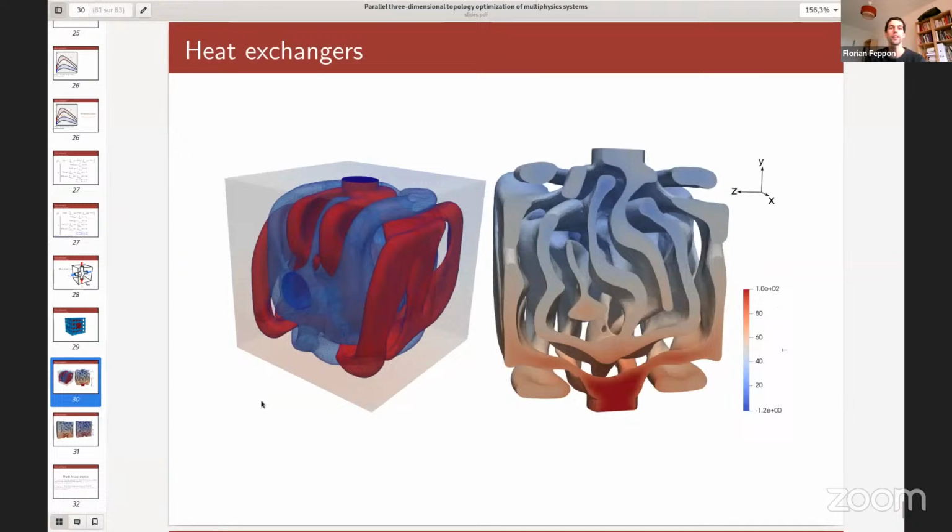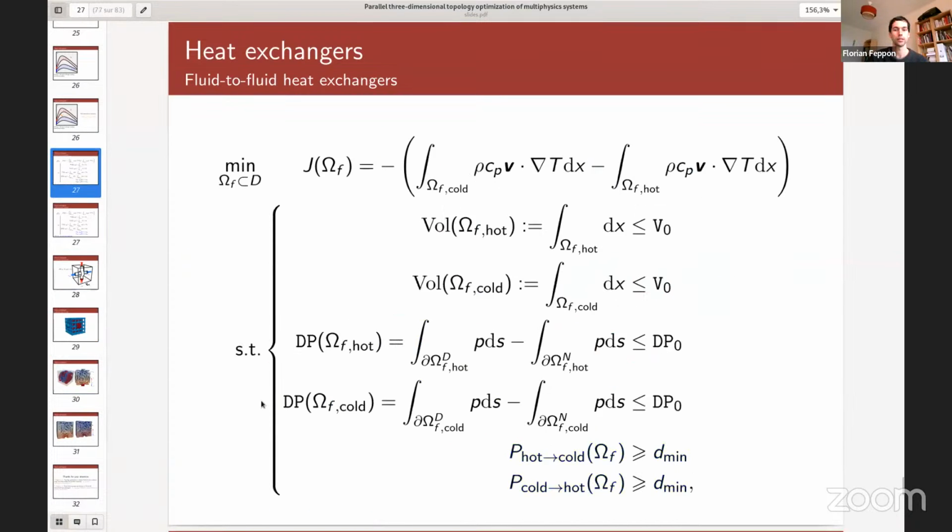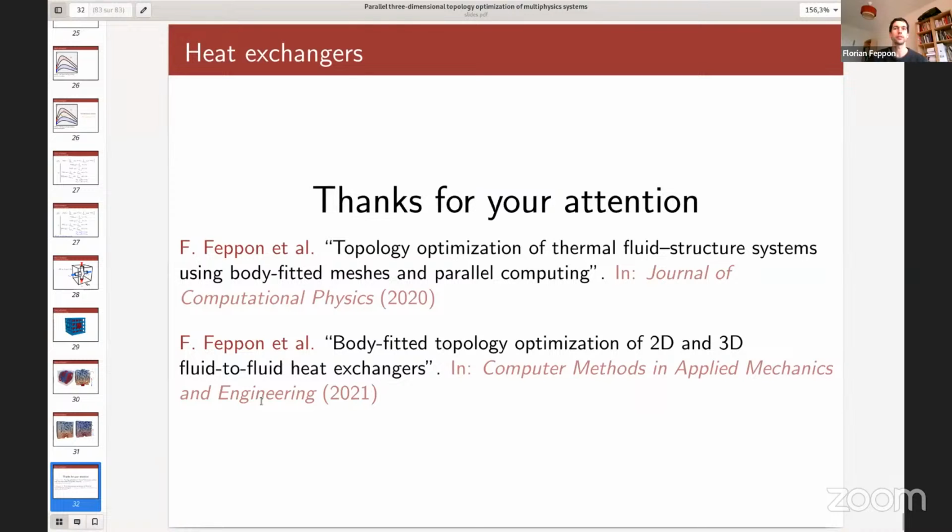Yes. In fact, with the library MMG, you can prescribe a maximum edge size on some boundaries, and also the gradation of the edge size. So you can really tune the edge size on different boundaries and say that you want a fine edge size on the inlet or on the outlet to capture boundary layers, or at the interface between two domains in order to have a very good approximation of the boundary, but also larger elements in the more homogeneous part of the domain.